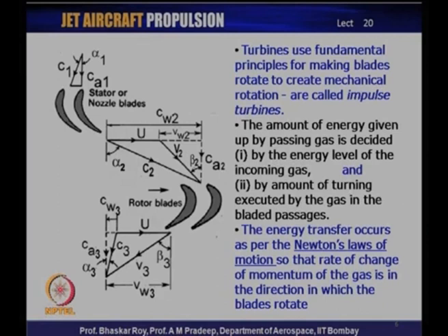So, most of the time when an aircraft engine is operational, the stator nozzle, specifically in the first stage of a multi-stage turbine, would almost invariably be choked, which means C2 would be equal to the local sonic speed, and hence local M2 would indeed be 1.